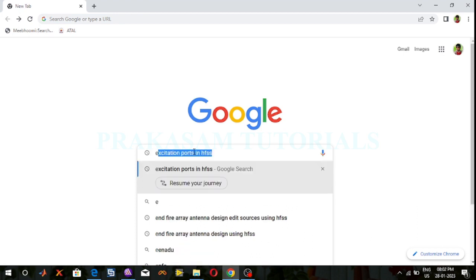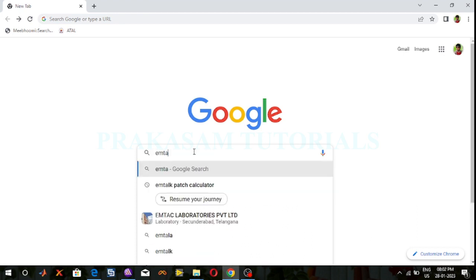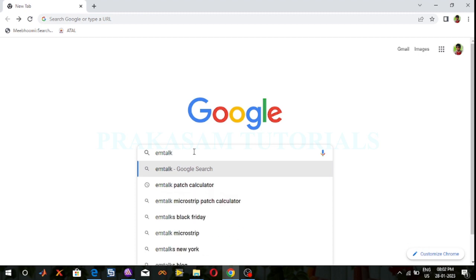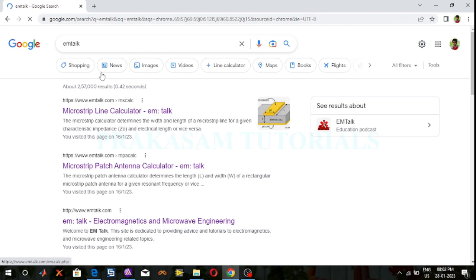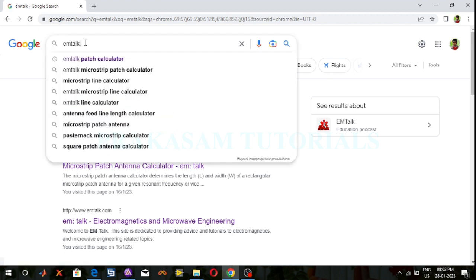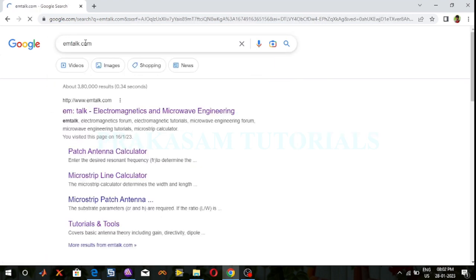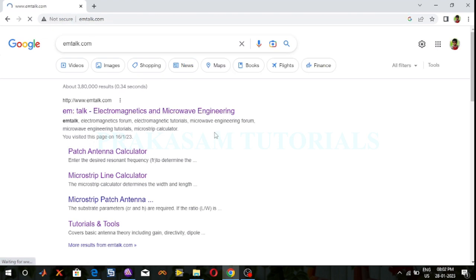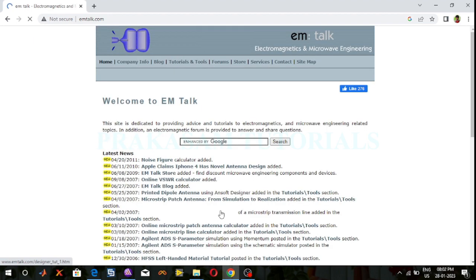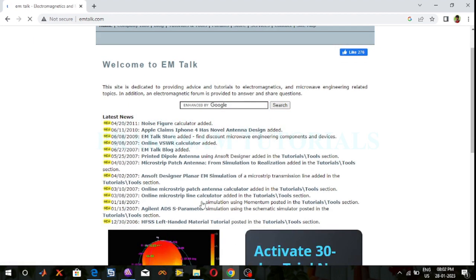In Google Chrome, enter emtalk calculator, emtalk.com. So click on this, electromagnetics and microwave engineering. So now here these are the online tools. Now here I am going to design a microstrip transmission line, so click on online microstrip transmission line calculator.